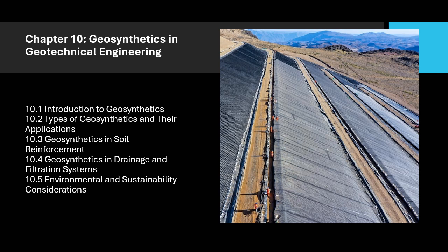5. Geotubes. Description. Geotubes are large, tubular containers made from geotextile fabrics used to reinforce soft soils. They are often filled with soil or sand to provide additional weight and stability. Applications.